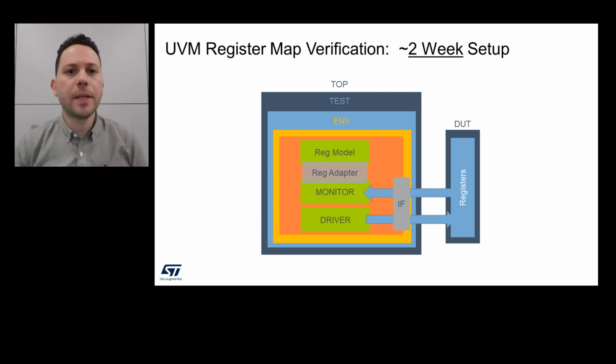STMicroelectronics' UVM environment uses Cadence Xcelium for dynamic simulation. UVM lets us verify the register map from top level, including the serial protocol and the integration of the CSR with the rest of the device. It takes about 2 weeks to first build an environment that stimulates the device correctly.